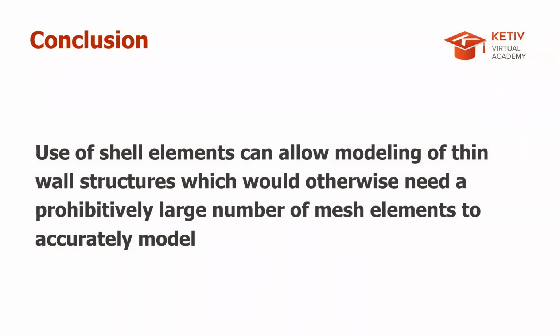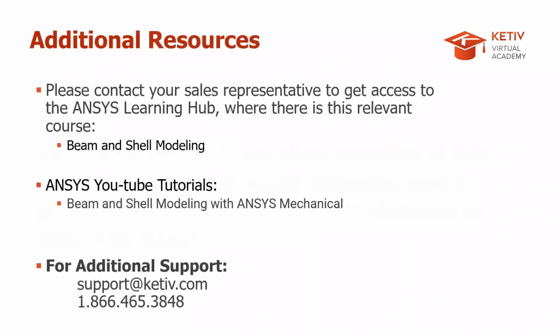The use of shell elements or shell solid elements can allow modeling of thin wall structures, which would otherwise need a prohibitively large number of mesh elements to accurately model. And that can definitely speed up your simulations. If you're interested in diving into more details about this, please do take advantage of the ANSYS Learning Hub, where there's a relevant course called Beam and Shell Modeling. The ANSYS YouTube channel also has a tutorial called Beam and Shell Modeling with ANSYS Mechanical.